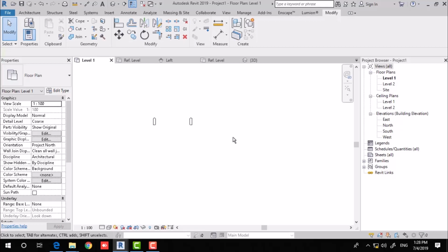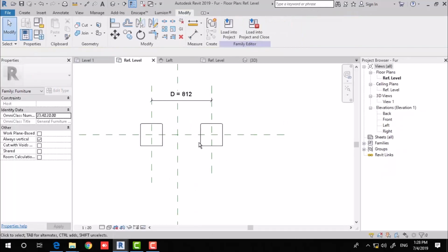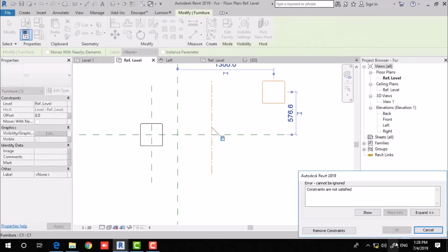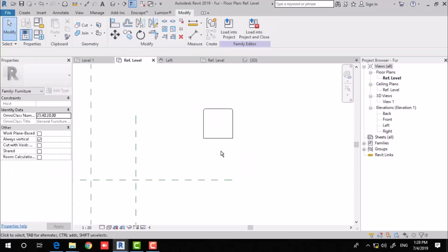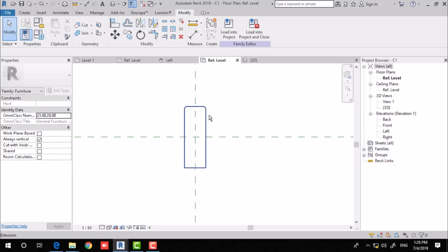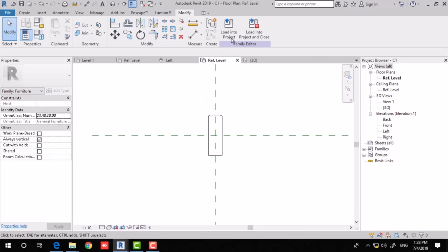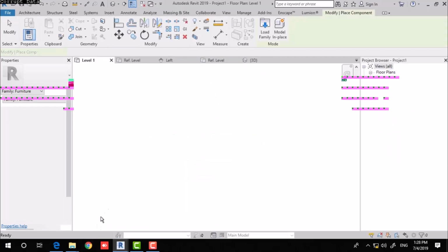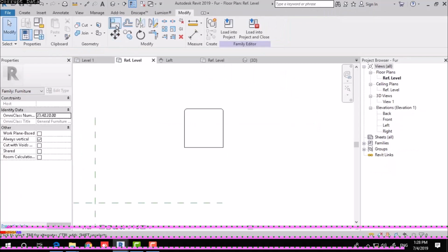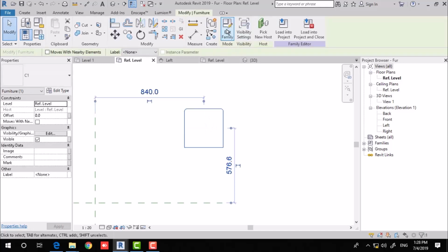What about the third topic? For instance, I open the edit family. Check this out. Here, if I consider this one as a nested family, I remove the constraints. I'm loading this family as a nested family. The positions in the source of the family, in which we have a sketch, are reference planes. As you can see, we got two reference planes which are crossing each other. If I load this into the project, we can use those reference planes for the alignment positions.